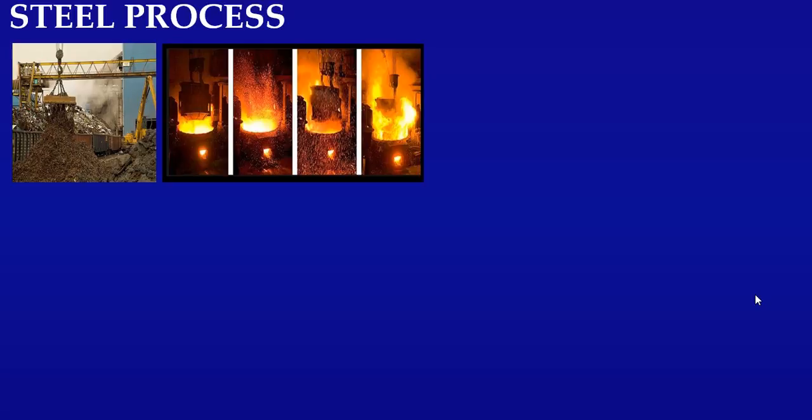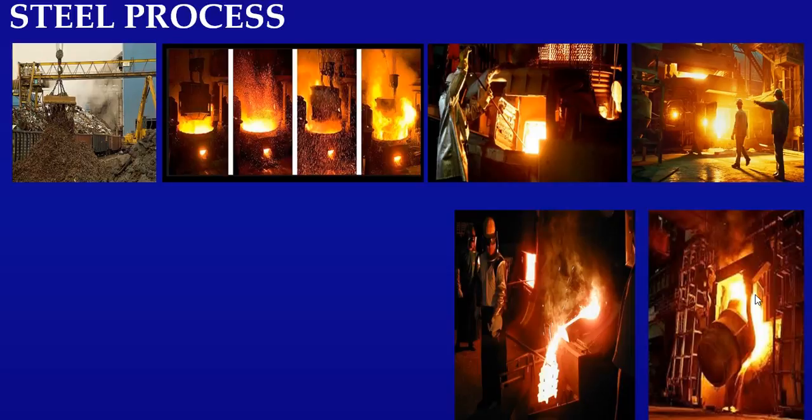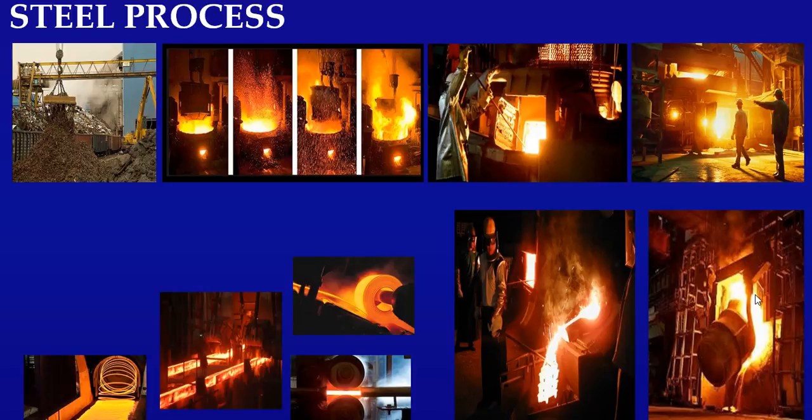Then it's necessary to take a sample to evaluate the composition of the metal and, if necessary, add more chemical components to improve the properties of the metal and decrease defects in the final product. Finally, the metal is refined to make a steel with better chemical and mechanical makeup. Then the liquid metal goes to the molds to obtain different forms, sizes, lengths, diameters, and different customer specifications.